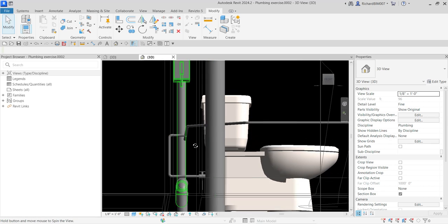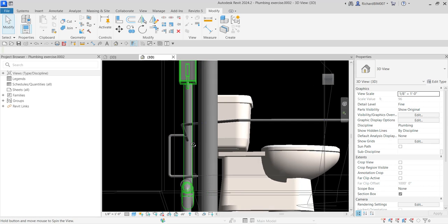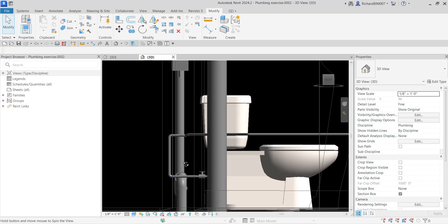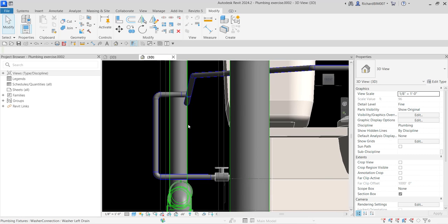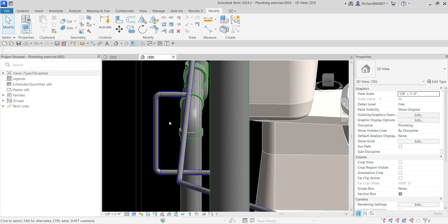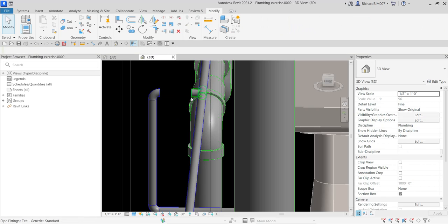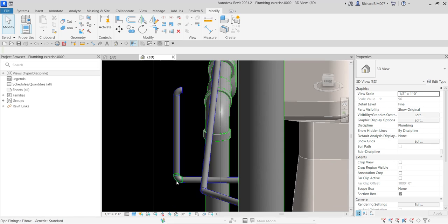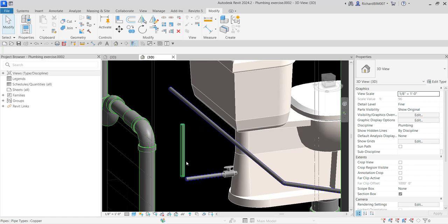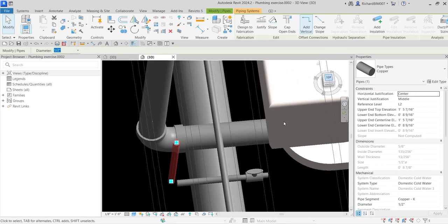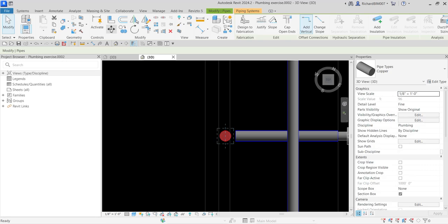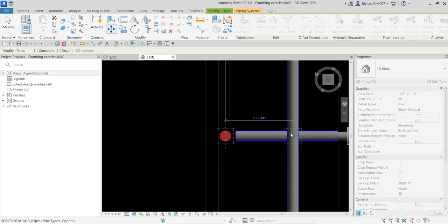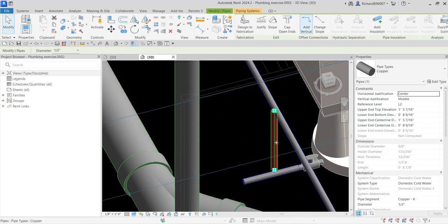It doesn't look nice. Maybe what I want to do here is create a pipe here going up and then connect there. There's too much of fittings and pipes here. Bad design. So let's rearrange. Let's click this pipe and then click that minus there to make it straight. Delete these fittings. Delete that. And then let's click this and go to the top view. Select that and then move. Pick the center and then move that at the middle. There you go. So much better.